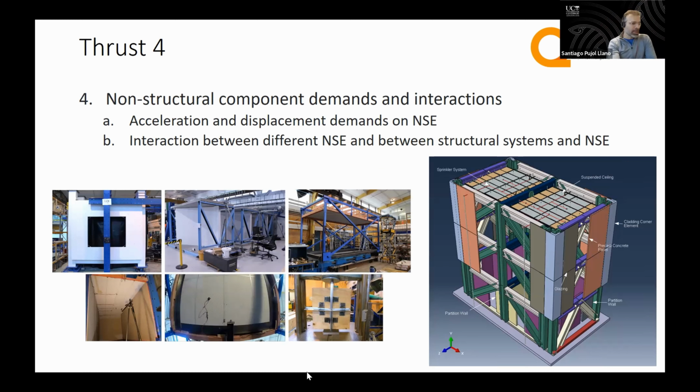I happen to know, for instance, there are firms right now struggling to decide what's the deformation tolerance, if you will, of cladding panels that were built maybe a couple of decades ago without clear consideration for their deformability. It's not easy. We don't quite have the methods to decide how much you can deform a structure before conventional attachments to the cladding pop, so to speak.